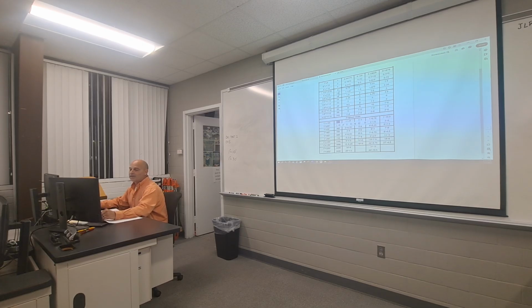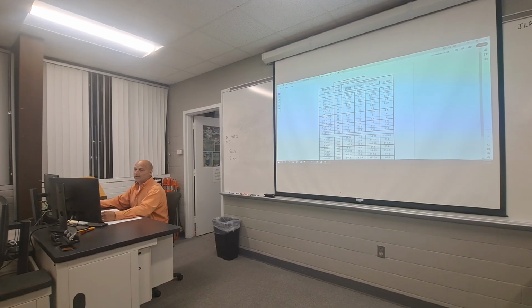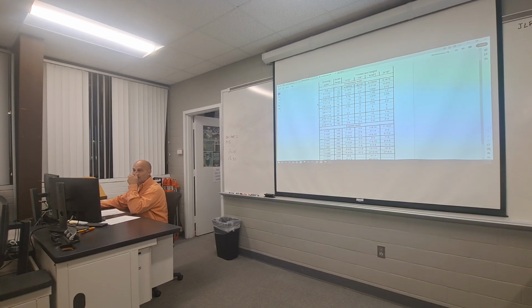Up until now, the biggest thing you had was your dimensioning, which, as long as you did your drawings correctly, was a fail-safe. So on the bottom of each one of these, they have that scale factor. Next to it, the next column, is the one you possibly used a good bit with me: printed text height, either 3/32 for general text, 5/32 for label text. Your N for your north arrow is considered label text. That would be an example of 5/32 text. All of our drawings in the civil world are going to have a north arrow on them, so that is one of your 5/32 texts.